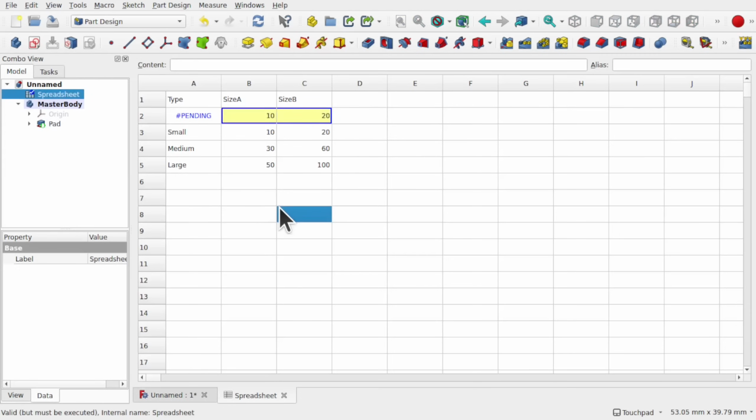We can add more configuration tables. So we could have a second one in here. Let's say for the pad, making sure we leave a blank line. I'm going to put in here high and low. One's going to be 5mm and the other one's going to be 1mm. And we'll alias up this field. Give it an alias of, let's go for size height.